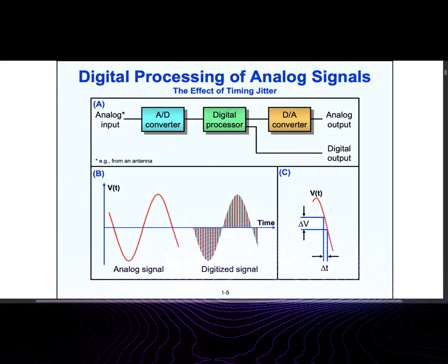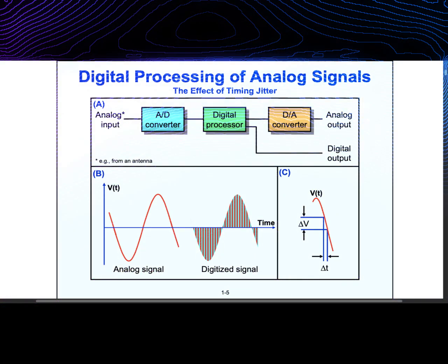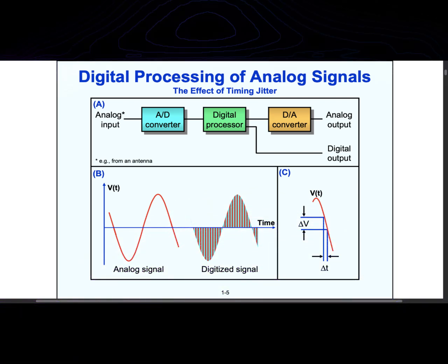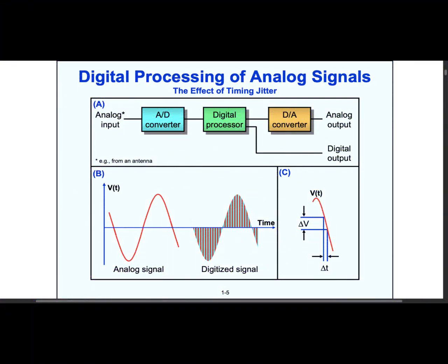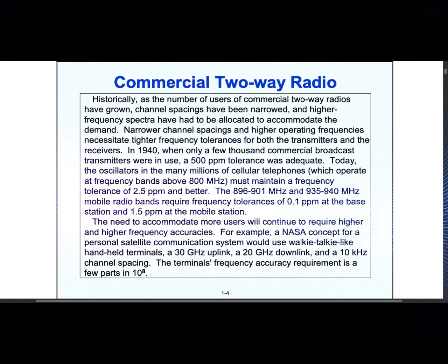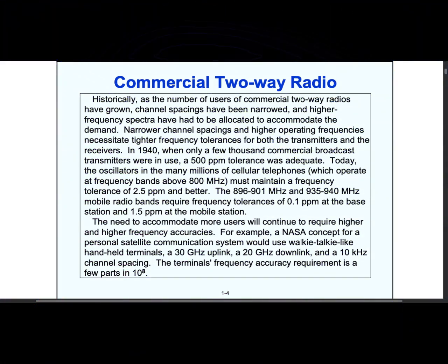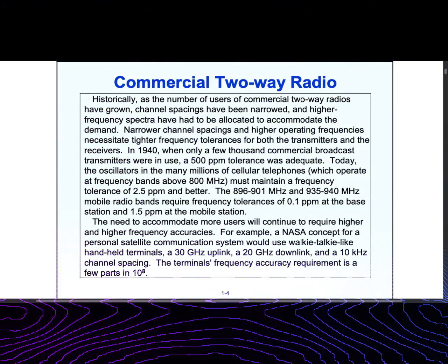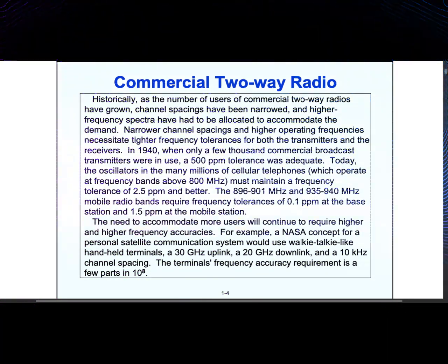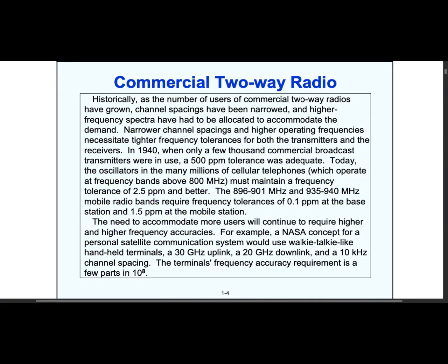Investigations have been carried out to identify useful orientations of the cutting angle of crystal plates, better known as blanks, for technical purposes and to characterize the resonant properties of the crystal plates that have been cut under a certain angle versus the crystal lattice. The so-called AT cut angle is the most common cutting angle to manufacture quartz crystal resonators with a very stable frequency over temperature.